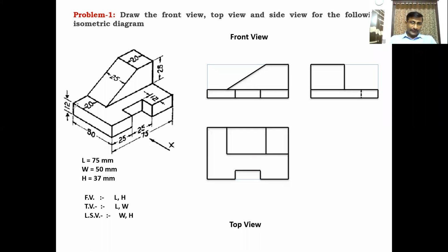Again I will explain. This surface is visible from the side view, and this inclined surface is also visible. This is the invisible surface, but this surface coincides with the surface, but this dark line is not there here. You have to draw the dark line. The dark line is a dotted line. It is invisible. So this is the first surface, the inclined surface, which will be a vertical surface here in the side view, which will look like a vertical surface in the side view. This is the first surface.